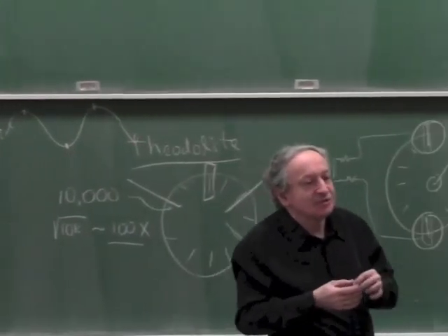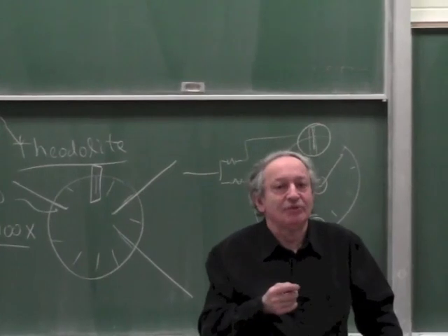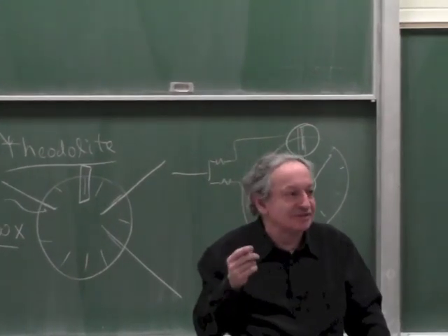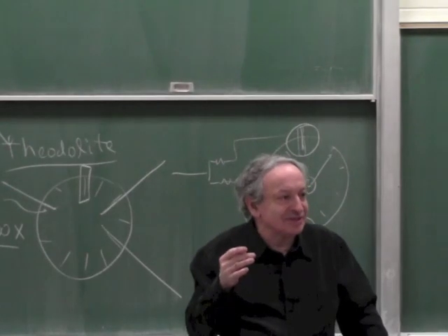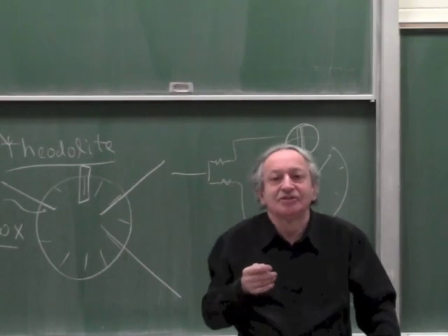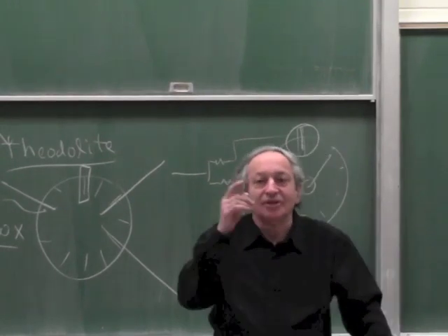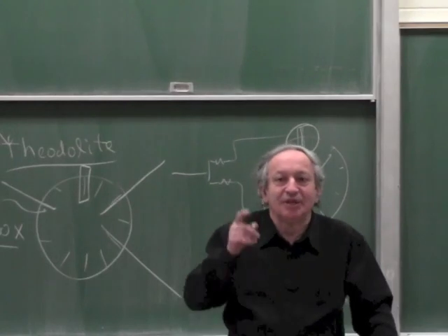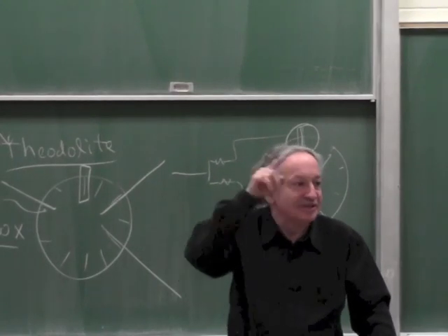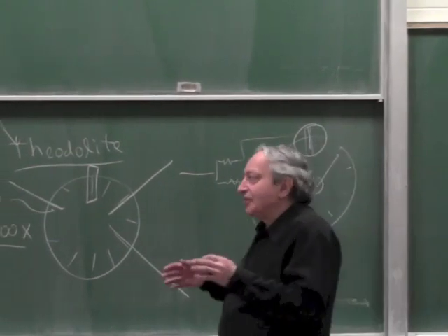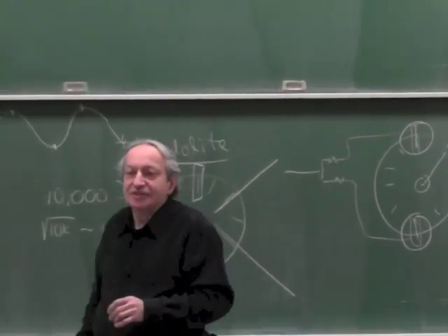It's basically not suitable to sense anything with information content of more than 15 Hertz. And even 15 Hertz is a limit, so let's say 10 Hertz. While a sensor which has a split detector and a light modulated at 100 kilohertz can easily pick up vibration of a few kilohertz and track it. Good. So that's a trade-off, but otherwise the camera is a very good sensor.